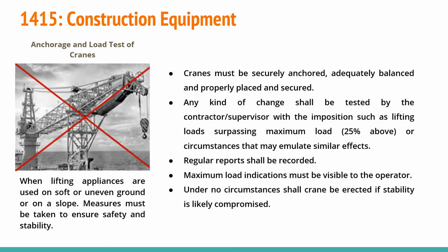Anchorage and load tests of cranes. It must be securely anchored and well balanced, because if a lifting appliance is used on uneven or soft ground, it will be hazardous and prone to accidents. It must be properly supervised and reports shall be regularly recorded. Maximum load must be indicated properly, and under no circumstances shall a crane be erected if stability is compromised.